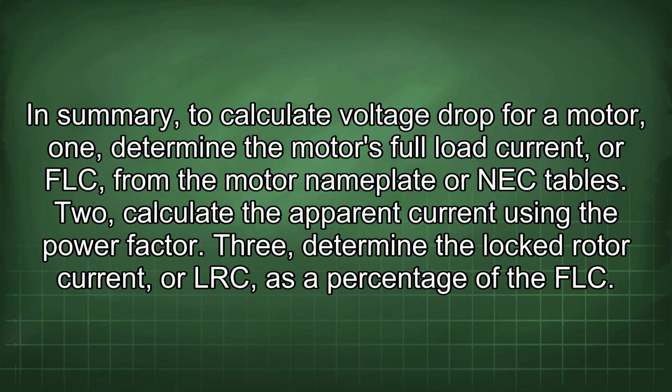In summary, to calculate voltage drop from a motor: 1. Determine the motor's full load current, or FLC, from the motor nameplate or NEC tables. 2. Calculate the apparent current using the power factor. 3. Determine the locked rotor current, or LRC, as a percentage of the FLC.